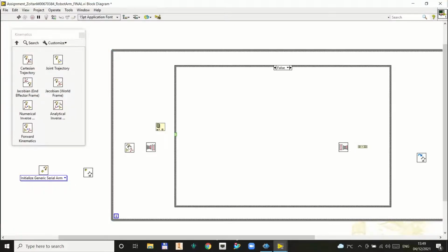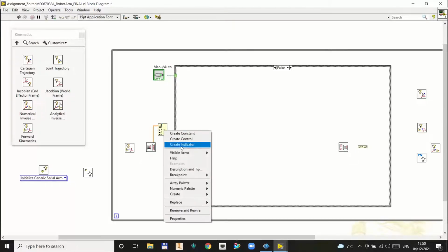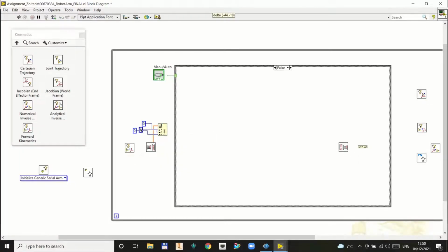The forward kinematics block is used to get the transform of a generic arm design. We get the translation vector of the homogeneous transform obtained earlier and index x, y and z separately in the array to be used and manipulated later on.